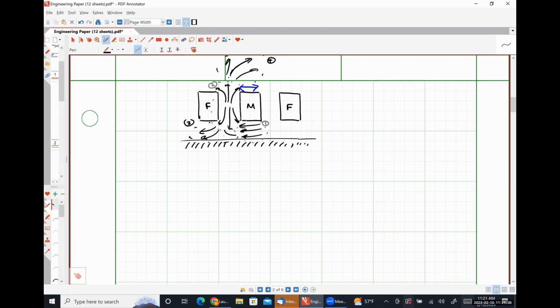Yeah, that's pretty much it. So for a simple structure like ones that we have analyzed multiple times in this class, we actually have multiple different components of just the air damping. And then we also have to take into account transfer of energy into the anchor losses, any surface roughness that we encounter, the intrinsic damping of the material itself, all of those things.